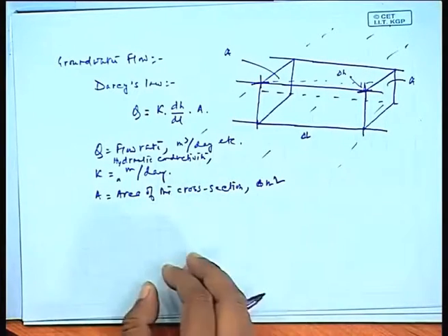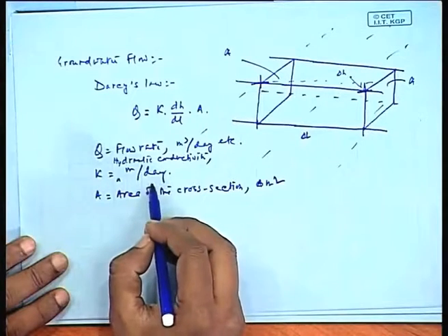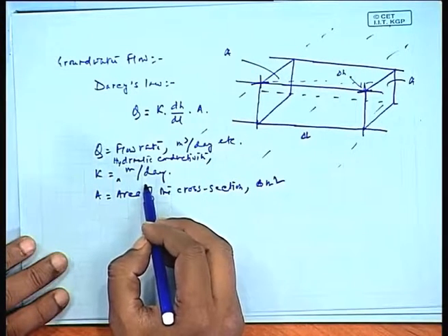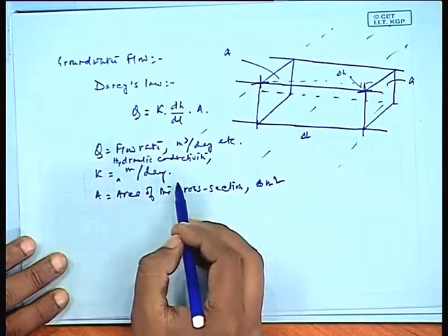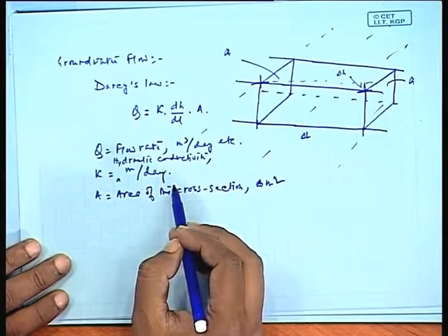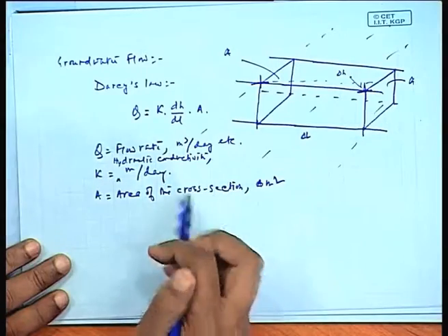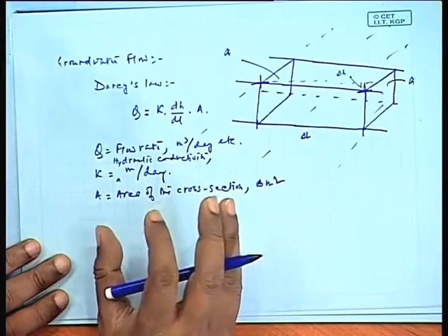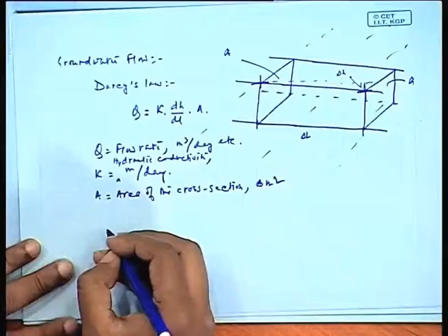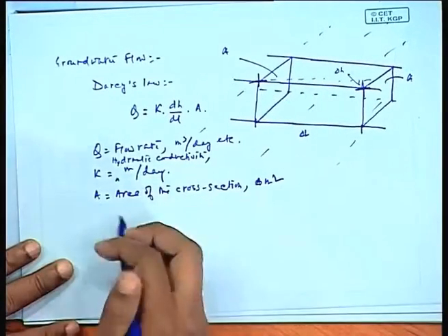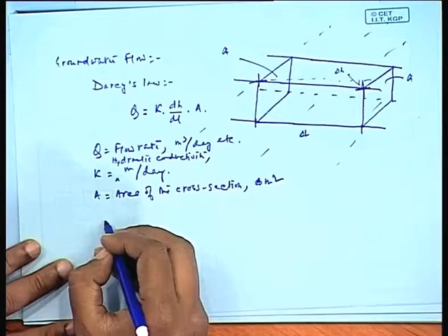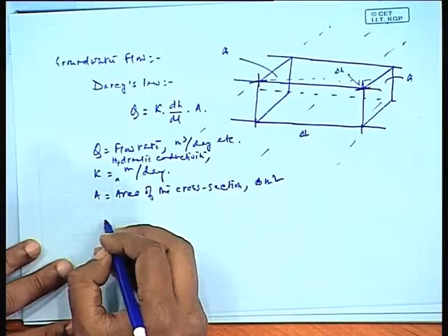That is how the condition is, meter cube per year, meter cube per day on the time rate coefficient, because in many cases the speed is very slow in aquifer, so we generally need not represent it in terms of minute or second. Mostly representing in terms of day is fair enough, because the velocity is very low. So you can see this is known as Darcy's law.